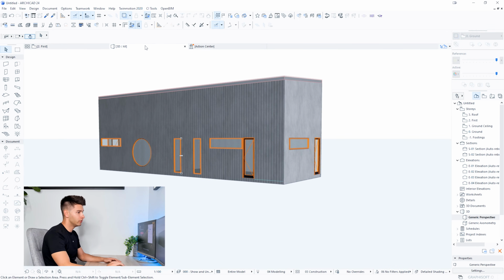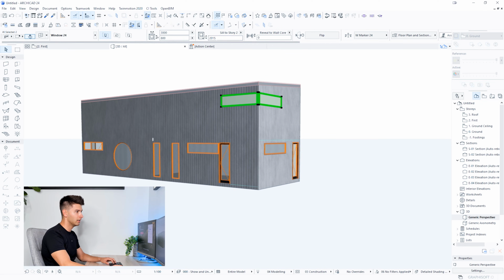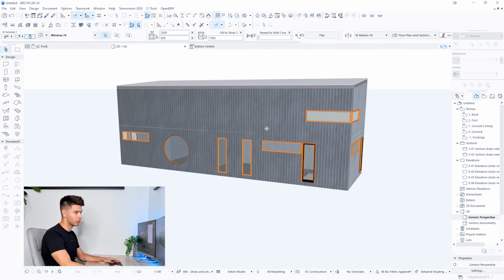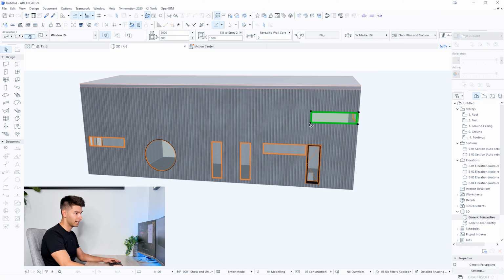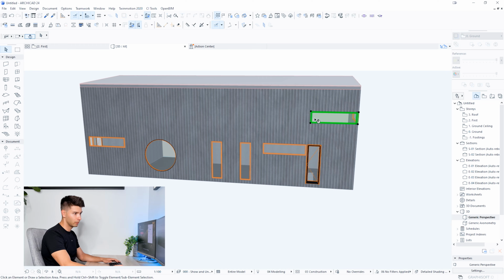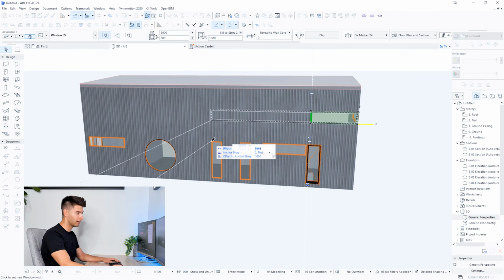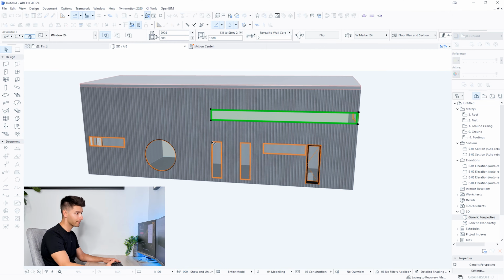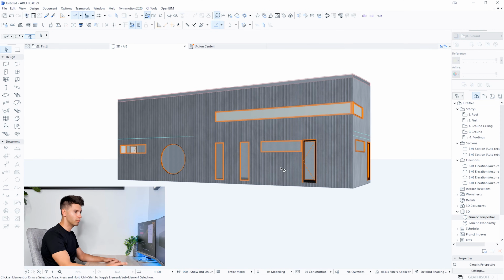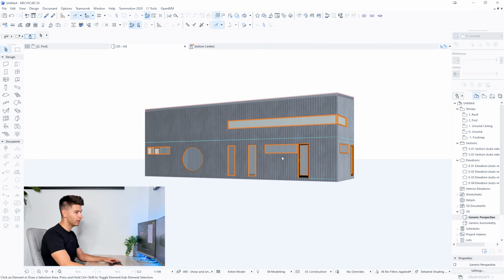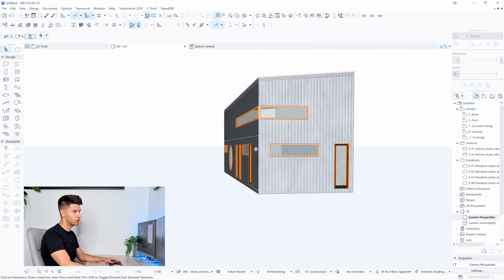Going back to the 3D view, now we have our beautiful highlight window that's a little bit too high for my liking. Let's say we only want that 1 meter off the ground, so we change that sill height up here and create that corner window. Let's say we want this corner window to extend. We click on the window first, click on the black hotspot and drag that window out in line with this. It'll automatically snap, and we let go. Now we have this beautiful long single pane window, which would cost a small fortune, but that's okay.